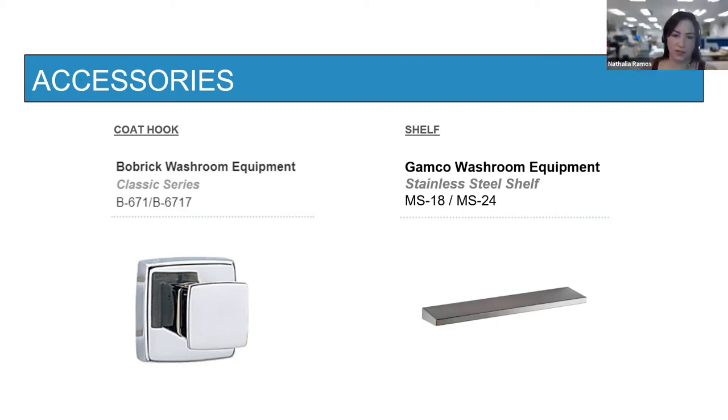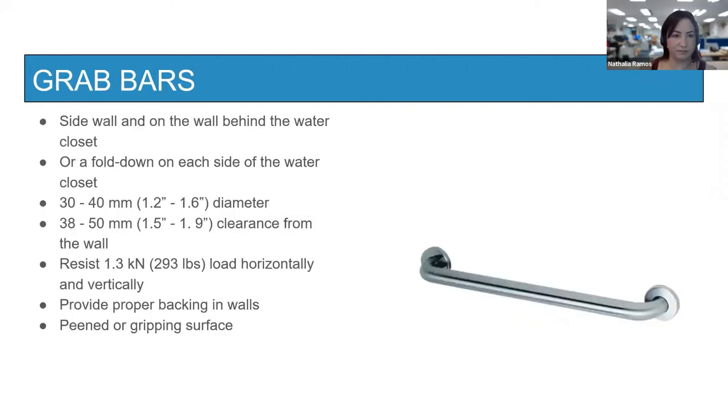Yeah, one example is the shelf. The Bobrick shelf is ADA compliant in the US, but it doesn't work here for the OBC requirements. So here we are always specifying the Genko shelf, the only one that protrudes only 100.